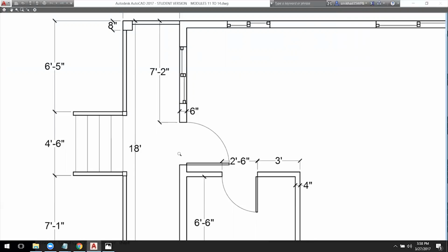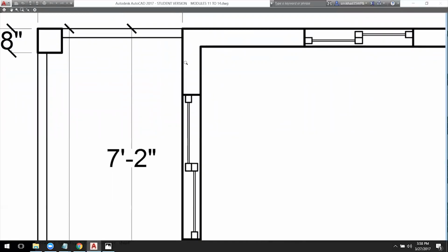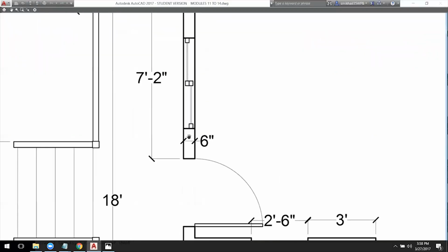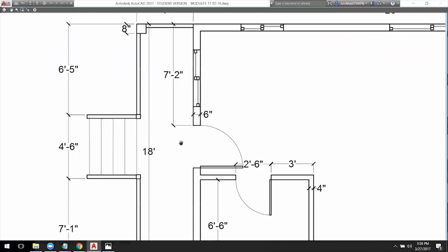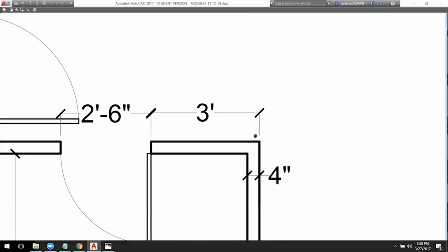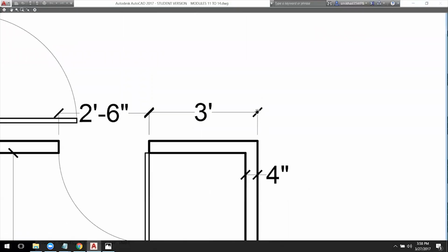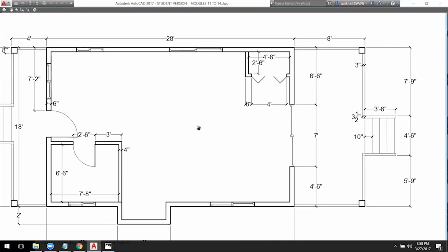It all depends on what the thickness is to the previous darker element. What you need to know is the rule of thumb, and that is the thickest on your drawing should be your walls. So when you zoom in here, you should see that walls are the thickest element. Then comes in any type of frames or railings, and then glass, door swings, and treads are generally the lightest of all. And as far as dimension, the string should be very thin and light, and the tick mark should be nice and dark, like you see in here.